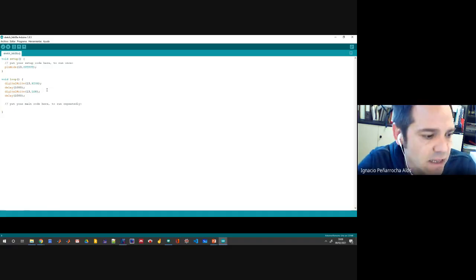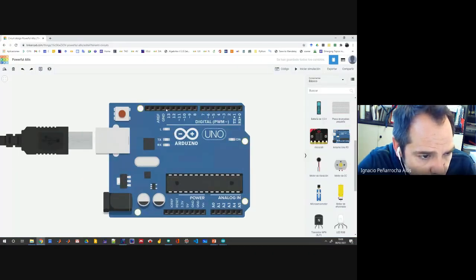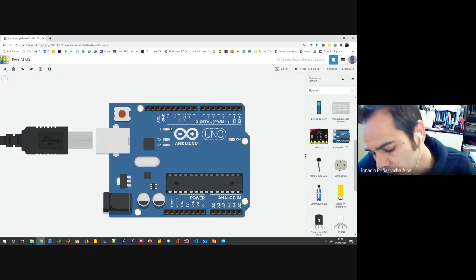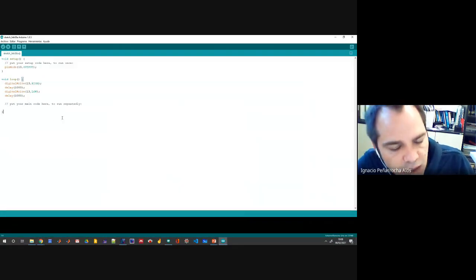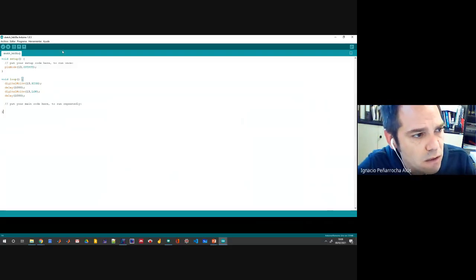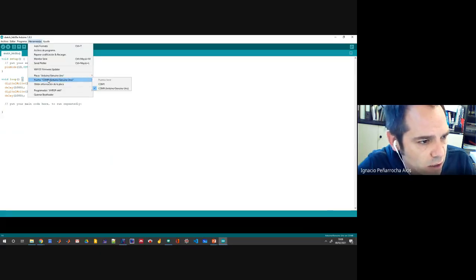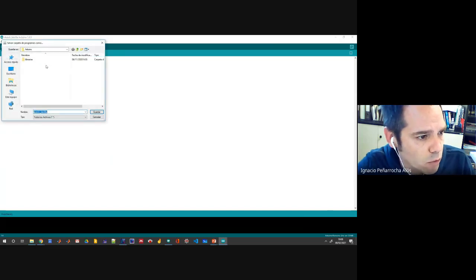The idea is that the microcontroller has on pin 13 an LED, so I will see it on my LED. Even if you don't connect anything, it's already connected on your board. If we were at the laboratory, we would connect it to this port, and then you would say verify or compile and download the code. I'm going to download the code, okay?